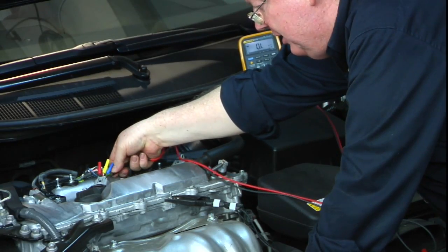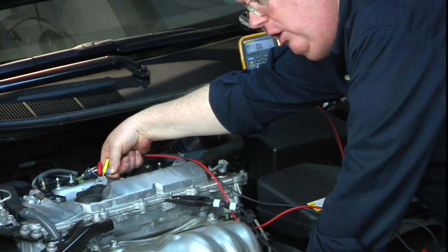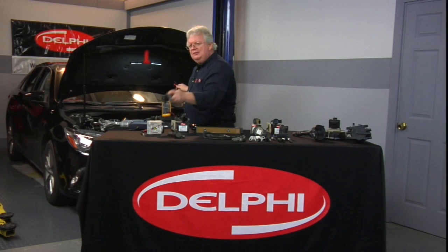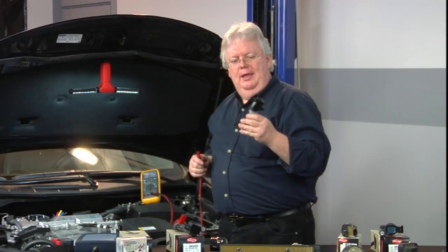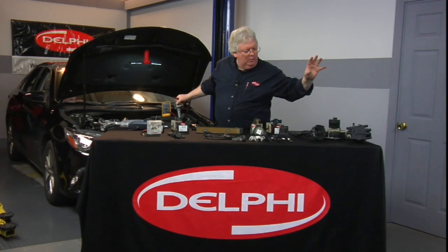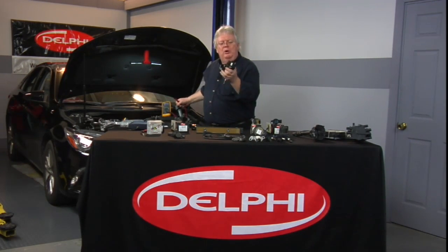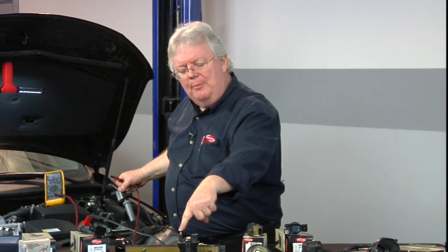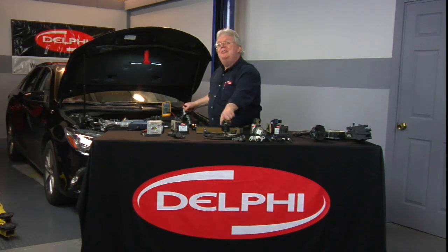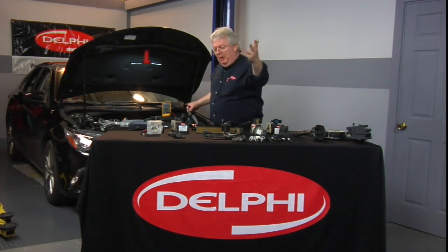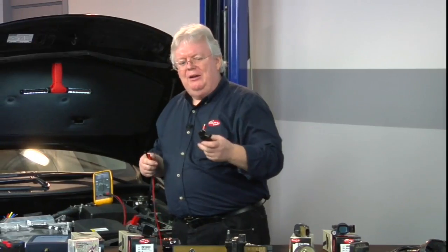In fact, that's going to be the challenge that we'll run into with a lot of these Coil-On-Plugs, is that if we use the old-fashioned meter to measure, let's say, this older Ford 2-wire C.O.P., and we go between these two terminals, that's the primary winding. Just like a good old-fashioned coil that we've used for years, an old tower coil, one of these old GM coils, we can measure between the primary windings. We have, let's say, a half an ohm, whatever. We can also measure between the secondary output and the primary windings, because the other side of the secondary goes to the primary. And the side of the secondary that goes then to the spark plug goes to the spark plug. You can't do that with the more modern 4-wire coils.